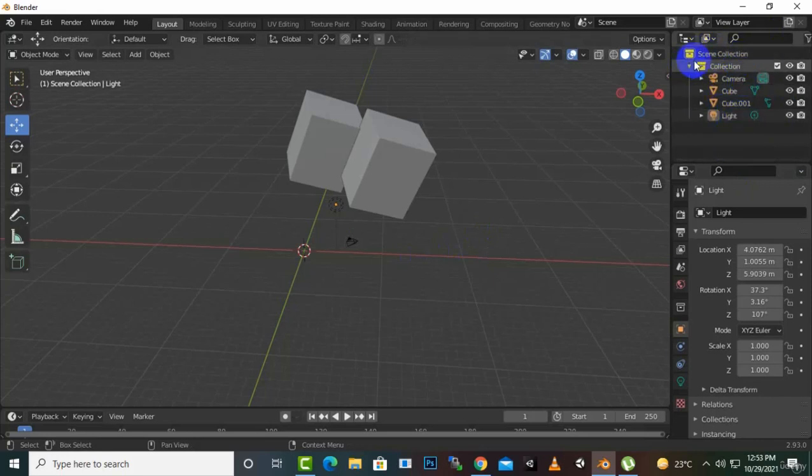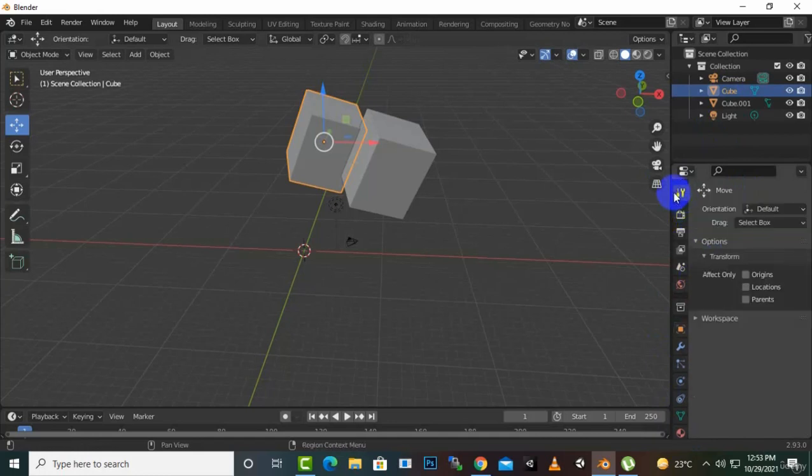After that we have this property window, and if we select this cube, you will see the properties related to the cube, and that is because we are on this tab. Okay, this property window also has these subsections. From the top, if we select this section, you can see that this is the specific tool which we have selected here, and these properties belong to this tool. Okay, so if we select the rotate tool, you will see here we have settings for the rotate tool.